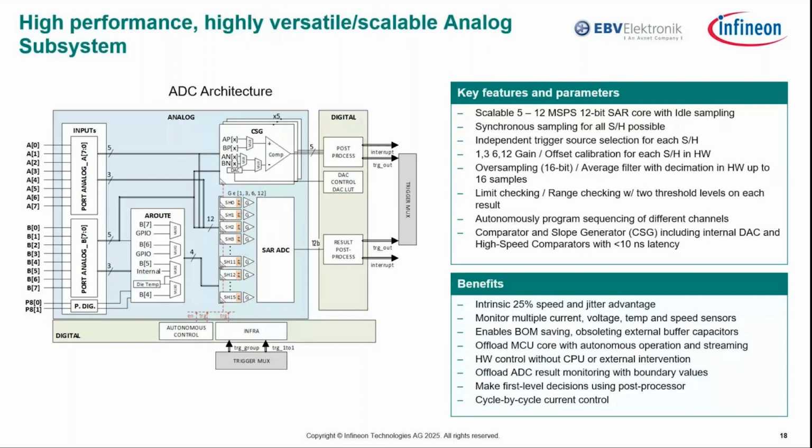Although we can read signals in parallel, we still need sequential processing to handle them. This is where the sample and hold features help us. It allows signals that are read simultaneously to be held until they are processed. Since we know the expected range of the signals being read, we can use the range checking feature to eliminate abnormal values or just detect unusual conditions and take appropriate actions.